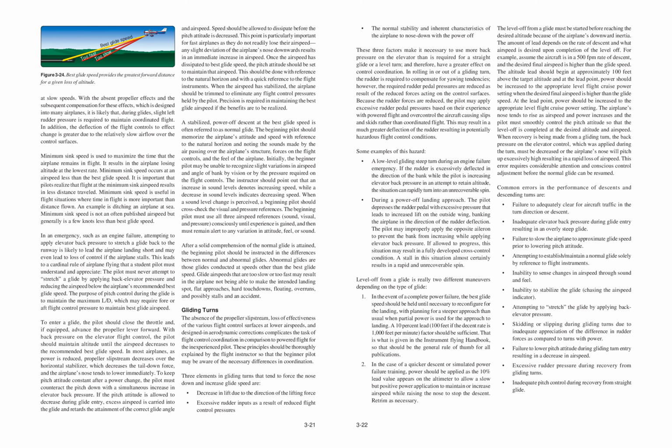Minimum sink speed is used to maximize the time that the airplane remains in flight. It results in the airplane losing altitude at the lowest rate. Minimum sink speed occurs at an airspeed less than the best glide speed. It is important that pilots realize that flight at the minimum sink airspeed results in less distance traveled.